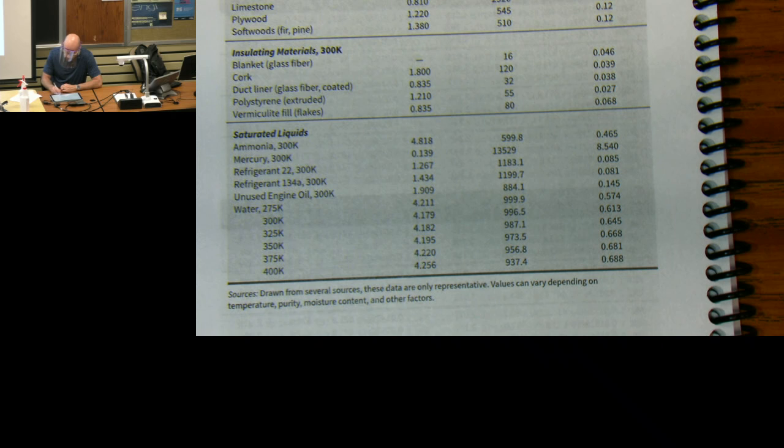Plus 0.25 kilograms times 0.385 kilojoules per kilogram Kelvin times T2 minus 30 is equal to 12 kilojoules. Okay, so here the only unknown is temperature 2. And when I solve for this temperature 2, I'm going to get a value in Celsius. Now, if you are uncomfortable with this, convert all your temperatures to Kelvin, plug it in the equation, your answer is going to be in Kelvin, then you'd have to back it out and give me the answer in Celsius. So whatever you feel comfortable with.